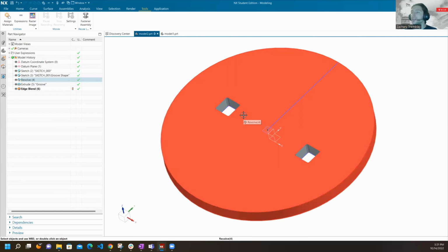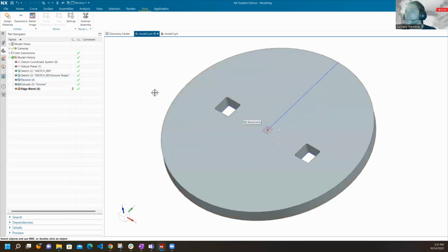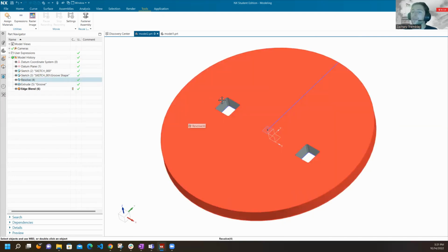So it's a relatively complicated process, but it's very, very useful in terms of if you know you want to change your design a lot, or if you want to have maybe multiple iterations, very useful to make quick changes. So it's just another trick. Again, variables can increase pretty much infinitely in complexity. You can have if statements. So if it's above this kind of diameter, you can have 3 holes or 4 holes.